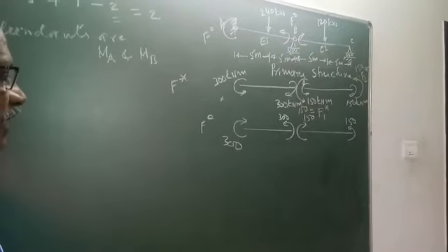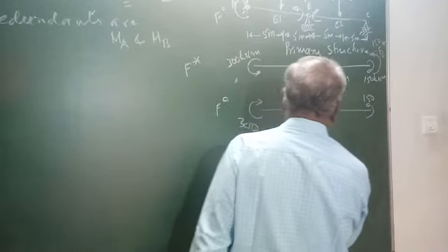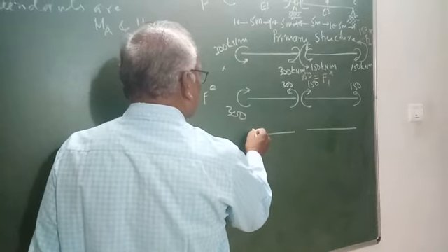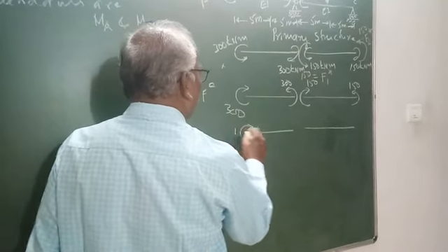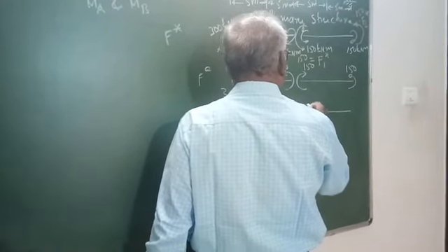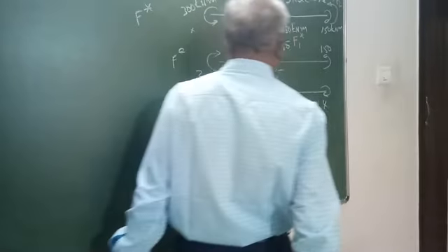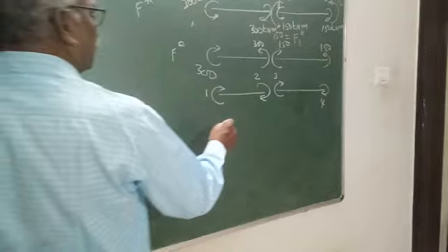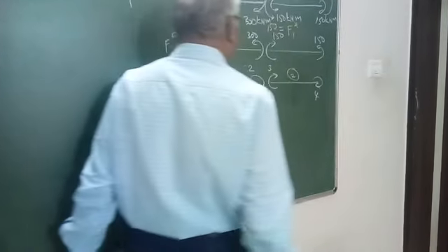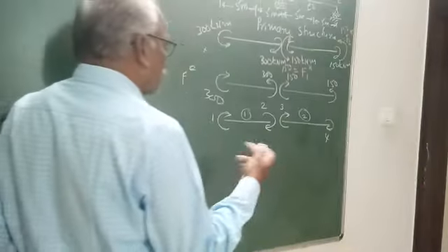Next, we have to find out the element coordinates. Element coordinates, this is 1. As we discussed, we have to mark all the coordinates in the clockwise direction, 3 and 4. We have divided the beam into two elements, element number 1 and element number 2. So we have taken only the moment coordinates.